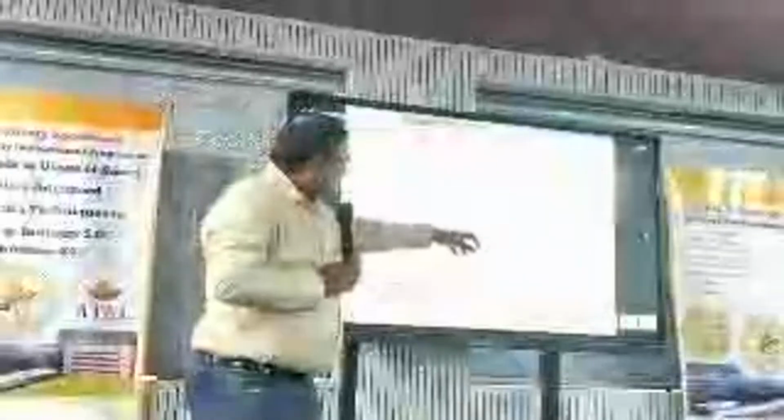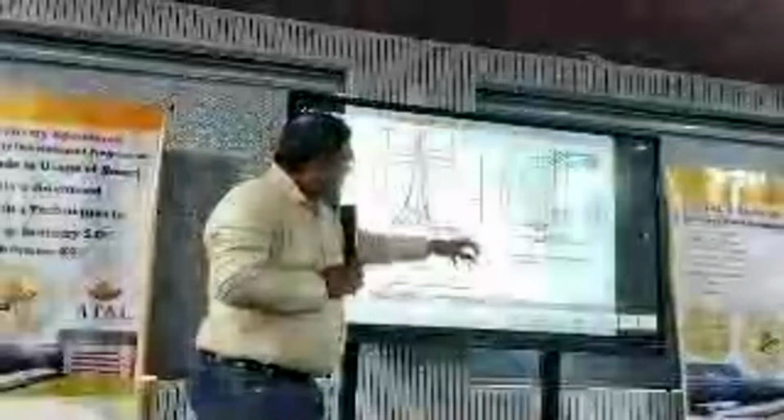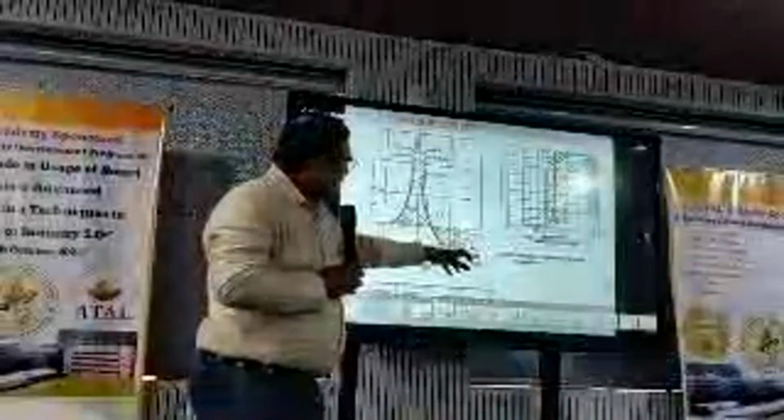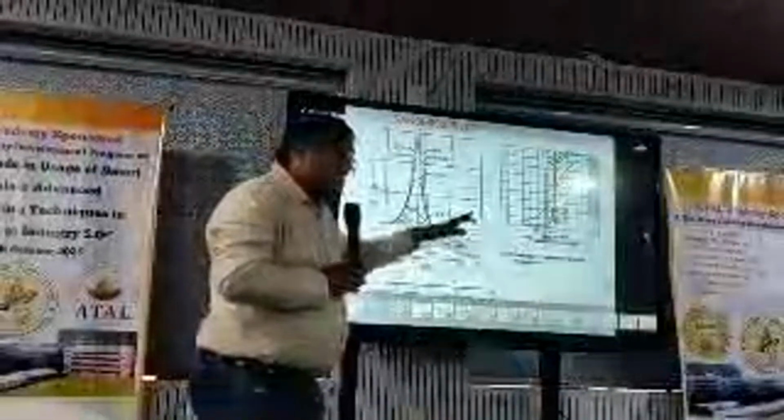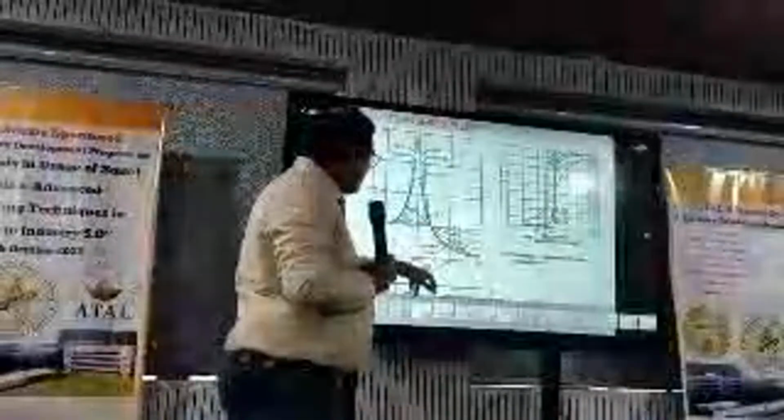In this condition also, with damping 2, 1, 0.5, if the damping is less in this region, less amplitude will be created, so it won't fail. So we have to design systems with omega greater than root 2. This is the root 2. Then our systems won't fail.